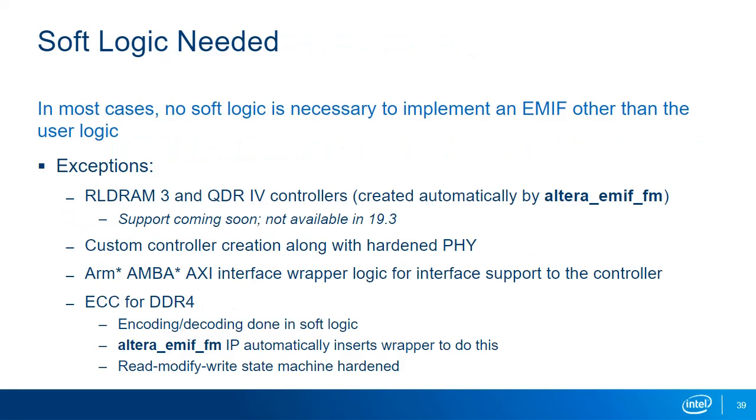For most designs, the hard memory controller and I/O banks form a completely self-contained hard solution for implementing an external memory interface. However, in some situations, it is necessary to add some additional soft logic between your user logic and the controller. These situations are listed here. If you are implementing an RLDRAM3 or QDR4 memory interface, the controller is implemented in soft logic when created with the Altera EMIF FMIP. The hard controller is only used for DDR4.